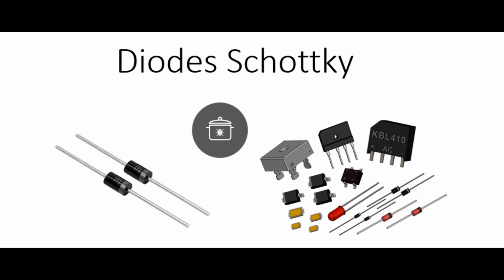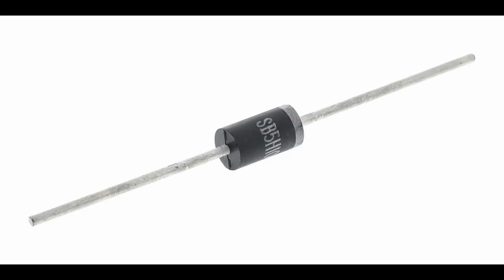There are different types of detectors, depending on the modulation scheme used in the communication system. Envelope detectors, used for amplitude modulation, AM, signals. Envelope detectors extract the envelope, amplitude variations, of the modulated carrier to recover the original baseband signal. Synchronous detectors, also known as synchronous demodulators, are used for phase modulation, PM, and frequency modulation, FM, signals. Synchronous detectors compare the received modulated signal with a reference carrier to recover the original baseband signal.